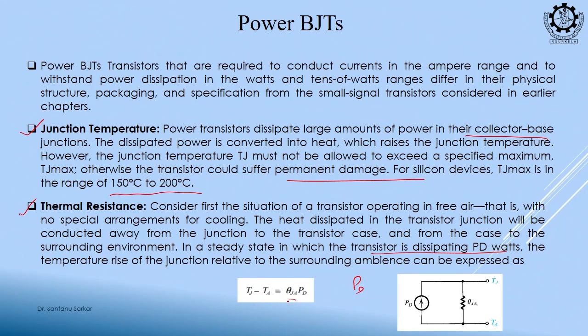So, it should be modeled by the maximum temperature it can reach, and the maximum power dissipation, and from this we model the thermal resistance.